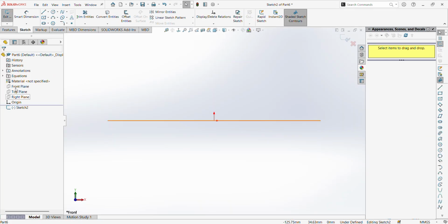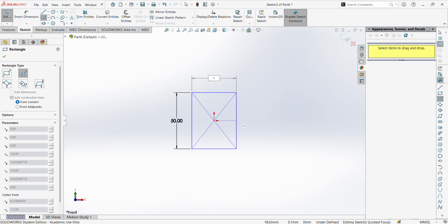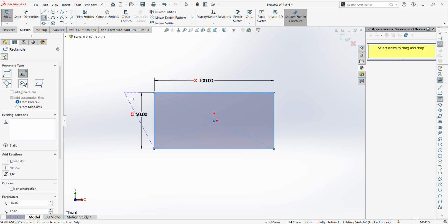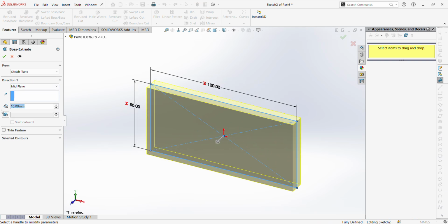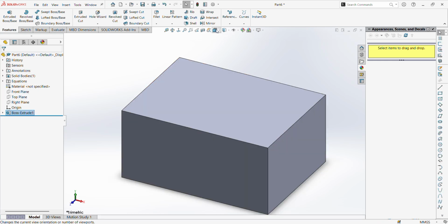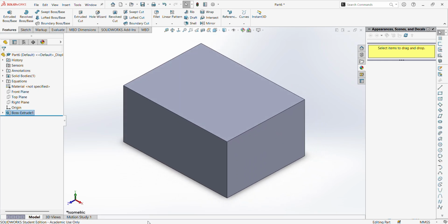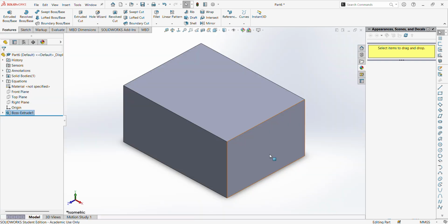So let's do this. We'll see how much faster this can be by center point triangle. We know this one to be C, so we're going to go equals quotation C, and that has to be capital. Boom. We know this one to be 100, so this one was A. Cool. And then we know the extrude depth to be mid-plane, and we know that one to be equal to the only variable we didn't use yet, B. Cool. So let's check our ISO, double check, make sure all the proportions are in shape. It is. Okay. So now let's look at this 3D sketch.